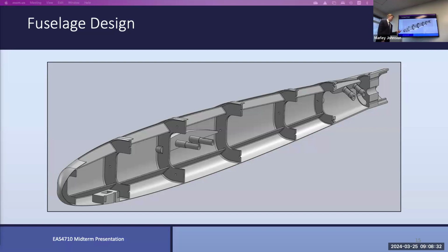I think that is one of the things we advised in the second phase we made. Yeah, so like your fasteners, I assume this is a full section. To me, your fastener wants to be tucked in near the longeron, rather than out here, where when the fuselage tries to bend, it's going to create a big moment that's got to carry through the cap of the bulkhead surface into the fastener.